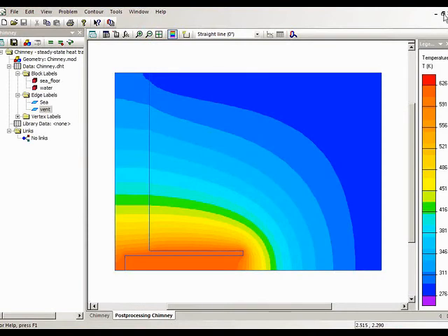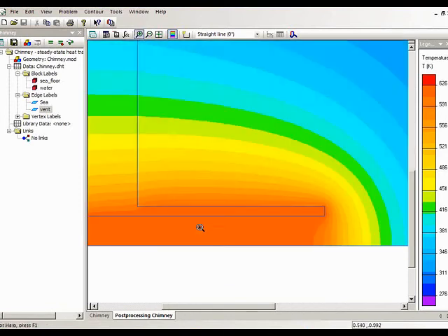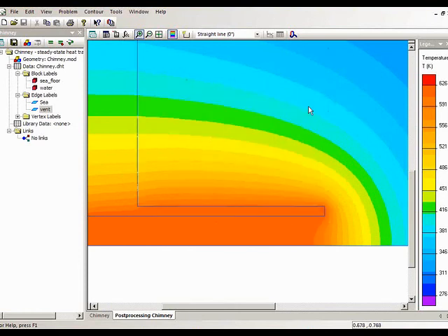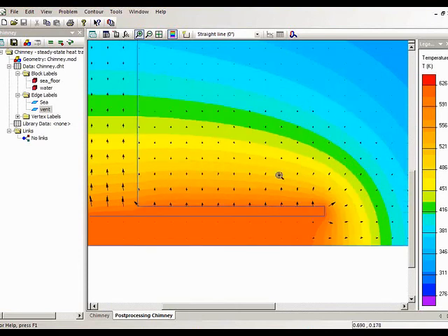And this shows us a contour map of our temperature surrounding the geothermal vent. And I can zoom in here. Also, we can make a contour plot of the temperature along any contour and the vectors of heat flux. You can see that they are flowing away from the vent feature here.